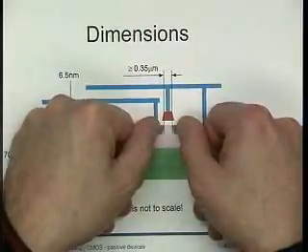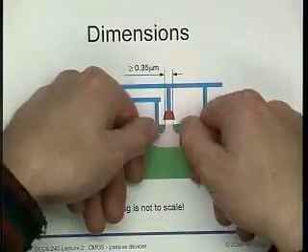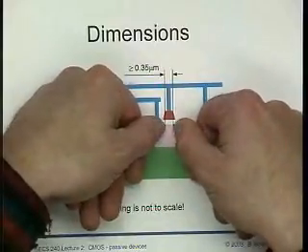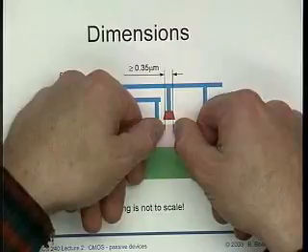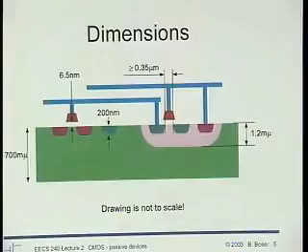Right? Also, if you come from a 140 background, then you know that there are really different kinds of lengths. There is a physical length that is really the physical distance between the two, and this is a PMOS transistor, so the two P plus regions here. And then there is also a drawn length you have on the mask that is a little bit longer, and then there is this LD business that accounts for the difference. It's one of the things that we are going to throw out the window in 240. Why? Because it just adds an extra parameter to our model.